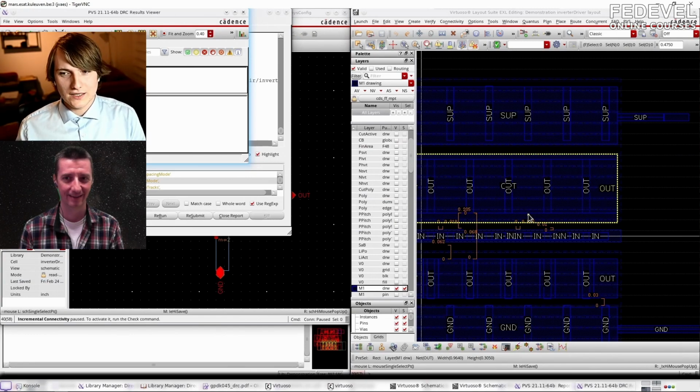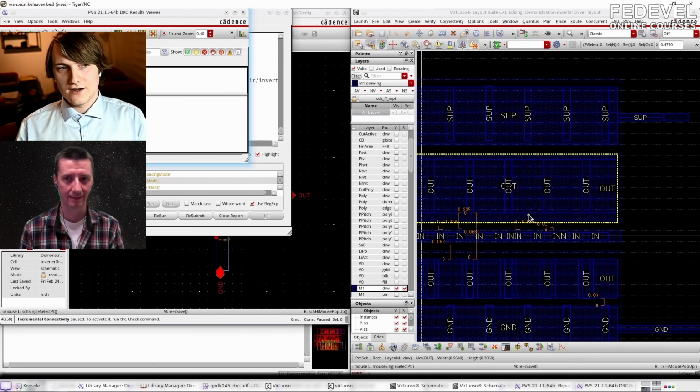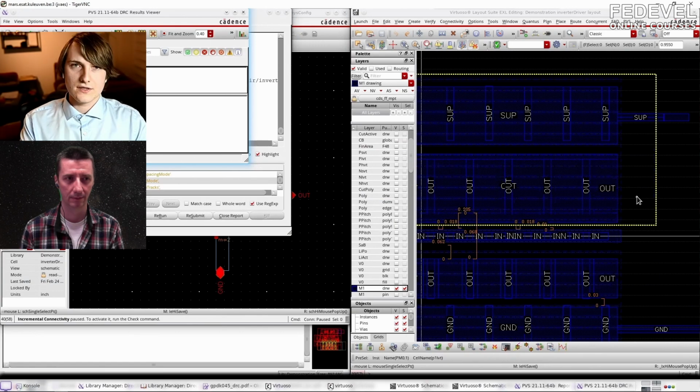If you go to millimeter wave, things get much more complicated because the models become more troublesome. It's much easier to miss little things that matter in simulation but don't matter in the schematic. But in general, you can be very confident that if it works with a parasitically extracted schematic, it will work when you receive the chips back.